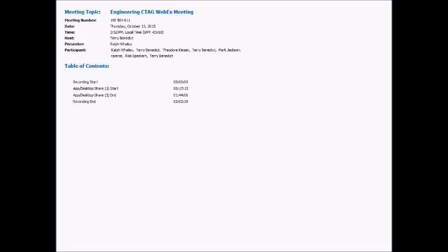I find with most of my students, when you hit the K-maps, we teach a vertical method rather than your horizontal method. I try to emphasize that the reason for the groupings is that when you get a pair or a set of four, the groupings that we teach, it eliminates one of the variables. We'll put the variables on the sides of the K-map so they can see that there's an A and a not A in one grouping, or a C and a not C in another grouping, and then eliminate those variables that way.